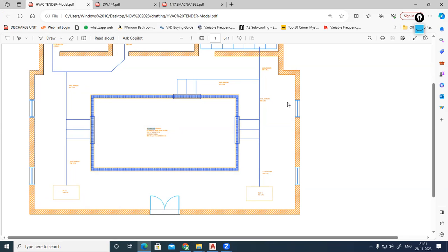Whether it is the local server way of working or the AutoCAD 360 way of working, you should not just double click and open your drawing and work. Drawing means architecture. When we are making our layout, which one will be our base drawing? The architecture layout. We will be getting the architecture layout from the architect. We will link that architecture layout, and only after that will we work. If you double click and open your architecture layout, it will come as a fresh copy.